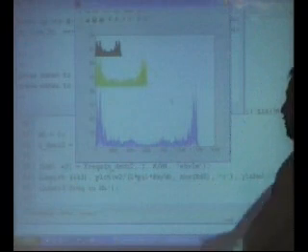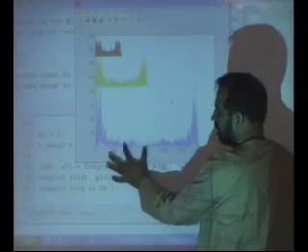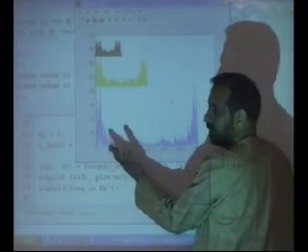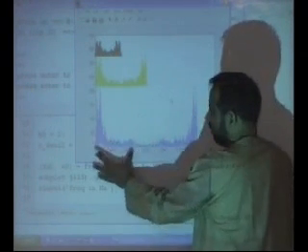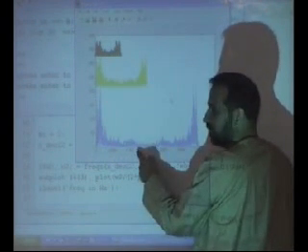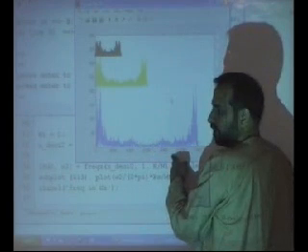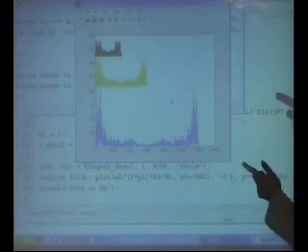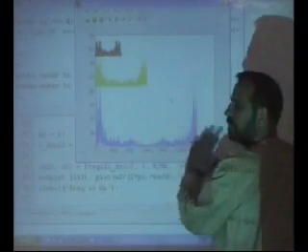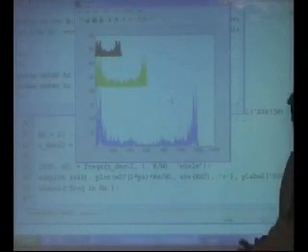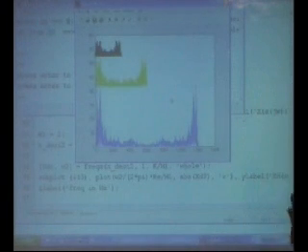Yes, there will be degradation, because you are throwing away some components in voice. Usually these are important components, but even in a telephone exchange, the signals are sampled at 8 kilohertz. They throw away anything beyond 4 kilohertz. For example, if you listen to music on a telephone, it is very bad because they throw away all high frequency content. They filter it out beyond 4 kilohertz, and then they digitize it.